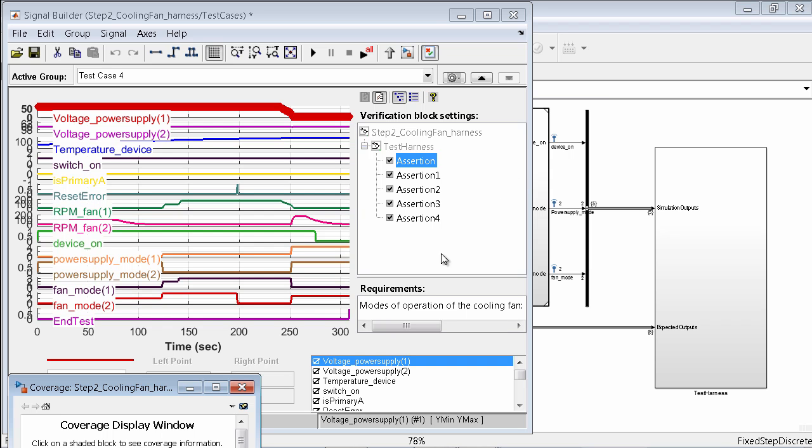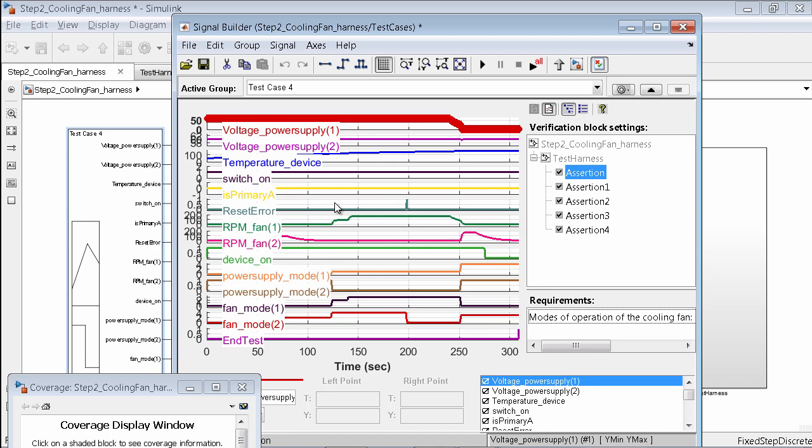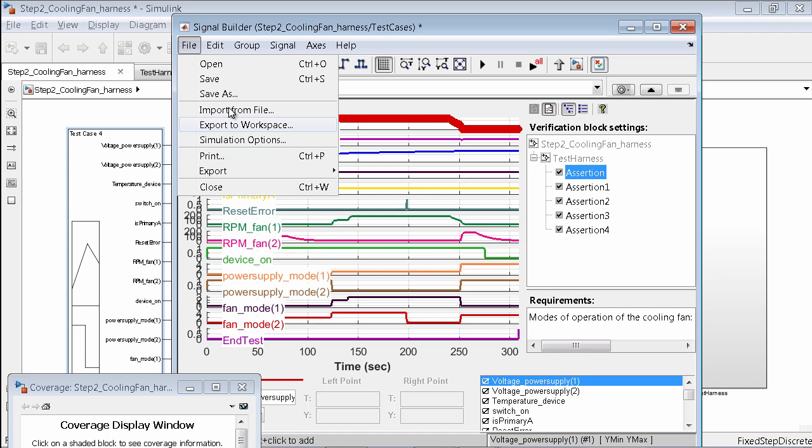One more question before we move on from this. These test cases that you've written, you talked about Signal Builder, but what other formats could they be coming from? I know our customers generally start from Excel or some format like that. You're right, that's a great point. I have used Signal Builder over here to manually create these tests. I've done this by hand, but we have a lot of customers who use Excel or CSV files to write up test cases. The tool allows you to import from files. So it's importing a test written outside of MATLAB and Simulink, getting it into this environment and setting it up for you. So yes, you can use Excel and CSV formats. You can even get data into the base MATLAB workspace, and we'll be able to leverage that as test cases as well. Excellent. All right.